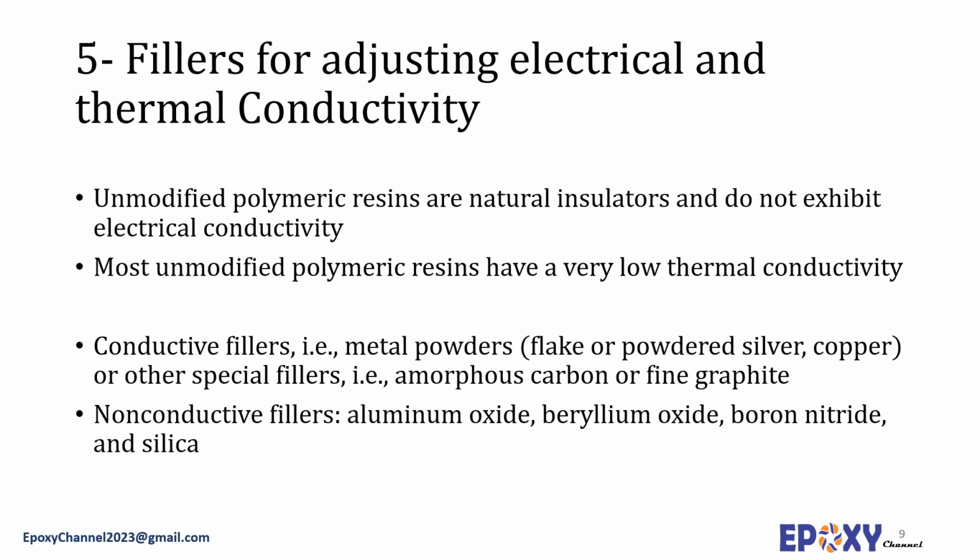Moreover, sometimes higher thermal conductivity and better dimensional stability are required from epoxy systems. Most unmodified polymeric resins have a very low thermal conductivity. There are certain applications where high levels of thermal conductivity are required. For example, power electronic devices and other heat-generating components are bound to heat sinks and other metal sources. Metal powder-filled adhesives, such as those described earlier for electrically conductive adhesives, can conduct both heat and electricity.